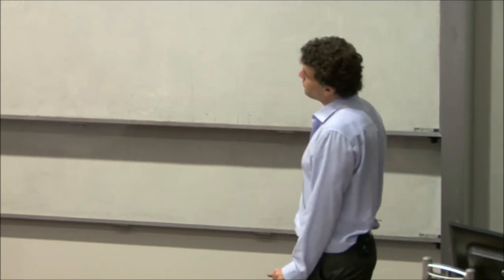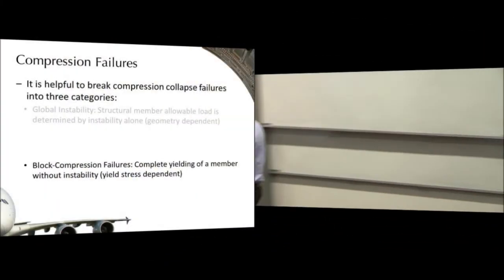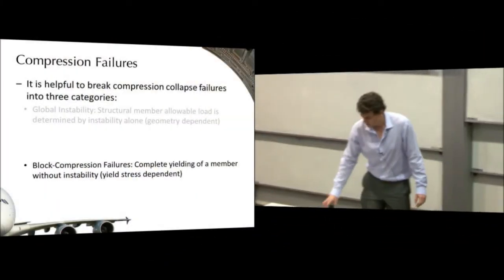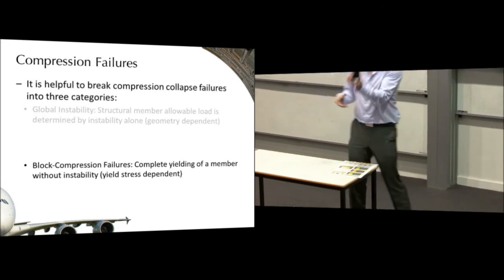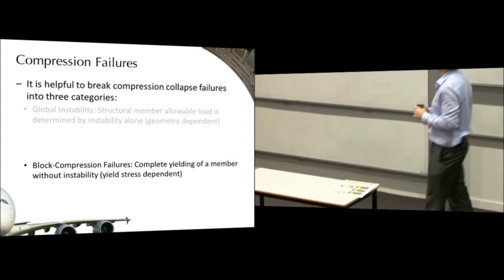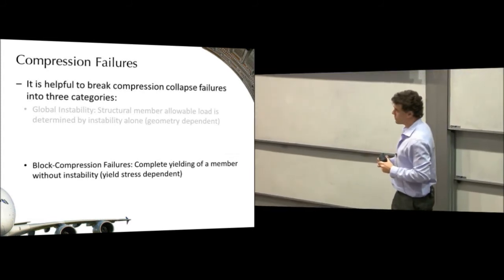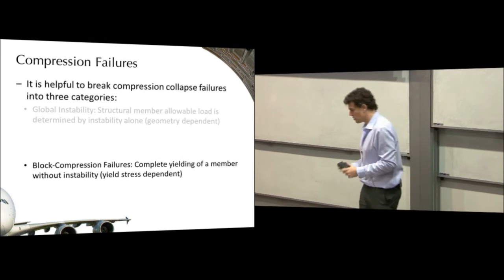We can have block compression failures. If I took this eraser or duster and I loaded it until it failed, it's not going to buckle, it's just going to yield and crush. So if the member is stout and thick, then we'll get material compressive yielding.